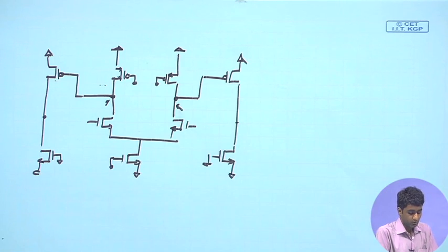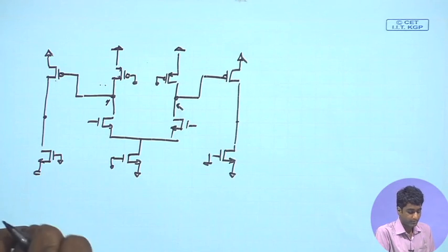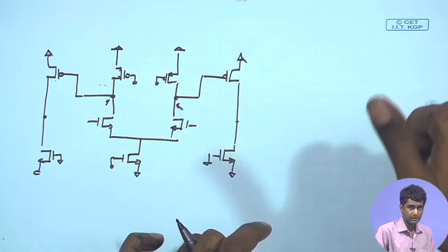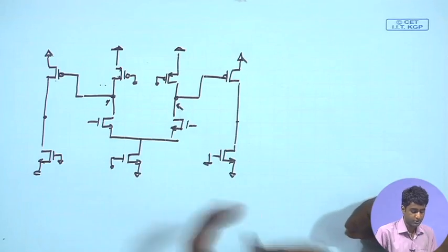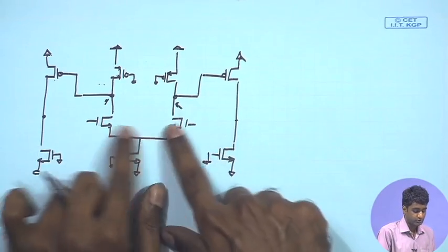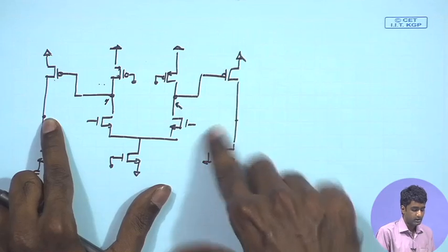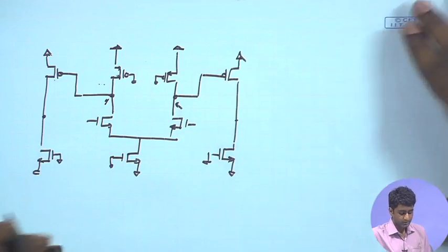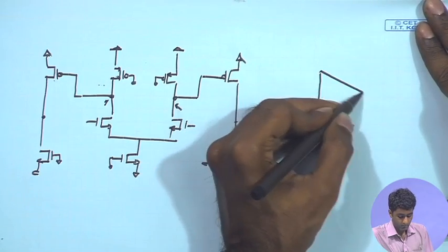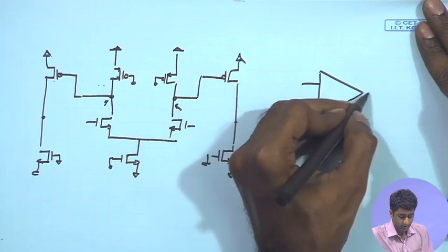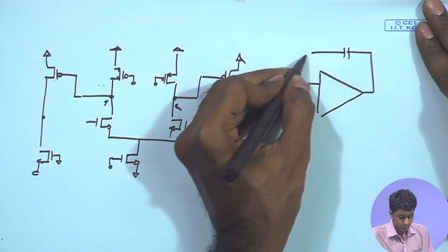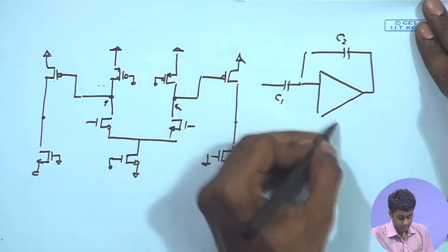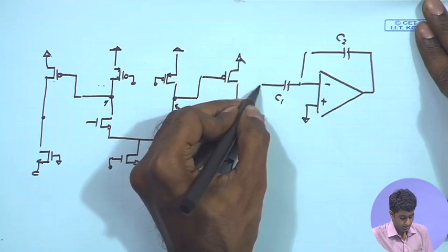So, we also looked at the feedback operation that we are applying over here. So, we need to look at the block level also, that how those feedback elements can come into picture to determine the overall loop gain. So, this is giving you the open loop gain of the standalone amplifier. We need to incorporate the loop gain coming because of the feedback operation. So, let us go back to the block level description of our feedback amplifier. Again, I am reverting to the single ended topology just for simplicity of the analysis, and let me call this C1, C2, and you have the input signal over here.